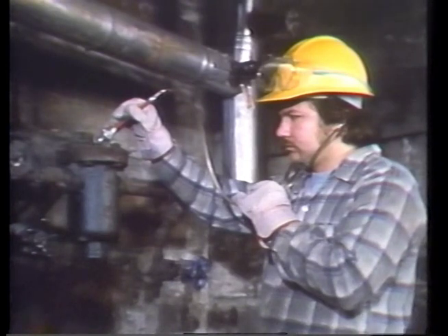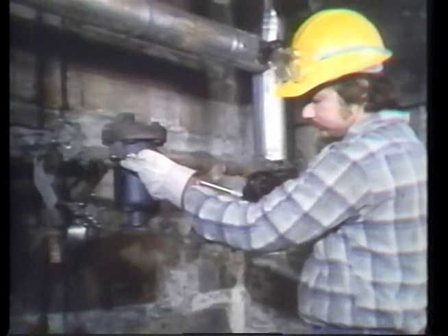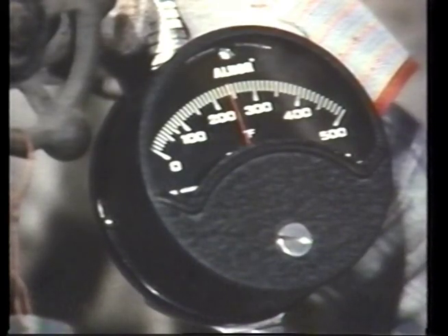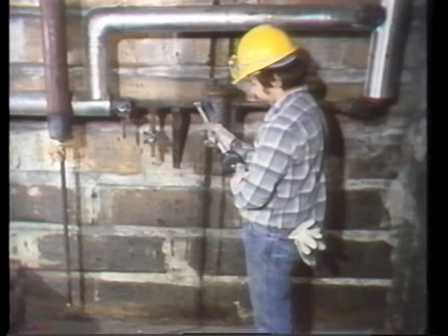We pointed out that where it is difficult or impossible to see the discharge from a trap, the sound method can be used. A stethoscope or other sound detecting device is used to listen to the trap internals. But you'll often find yourself in situations where loud background noise drowns out any sounds the trap is making. In that case, you may want to use the third troubleshooting technique, temperature. Measuring the temperature of the trap inlet and outlet piping is one of the most effective troubleshooting methods. But it usually requires more time than either the visual or sound method.